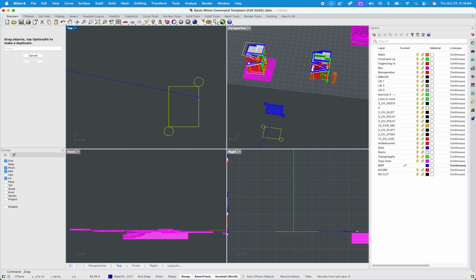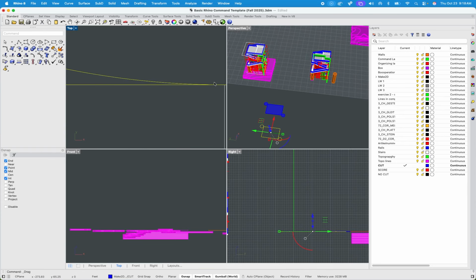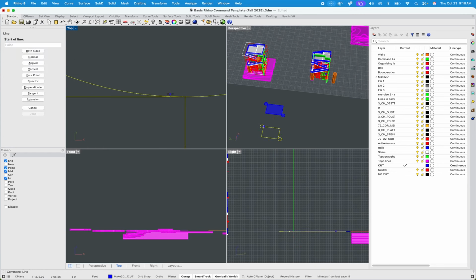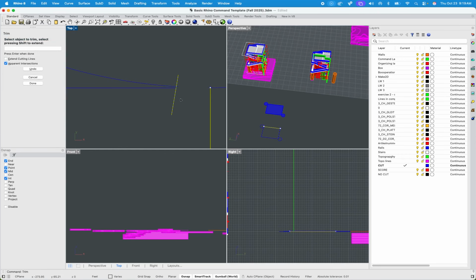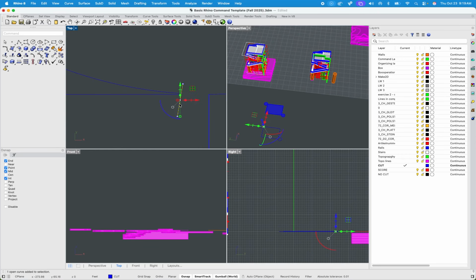However, to be fair, take a look. It's probably going to fall apart, especially if I just leave it the way that it is. Now, what I would do, knowing what I know, is trim it out. So I would actually ungroup this, because by default, make 2D is grouped usually. And I'd want to trim some of these pieces off, right? So I'd take these two, trim, and that is actually what I would laser cut. To be fair, I could cut off this as well.